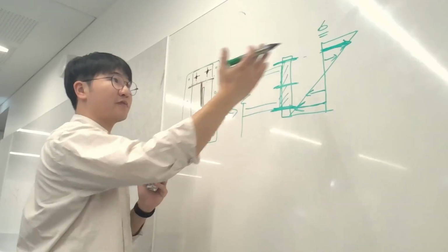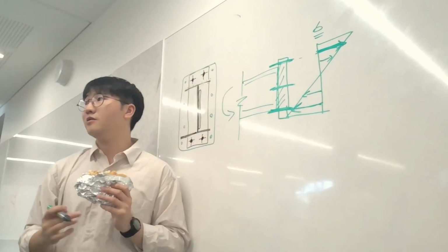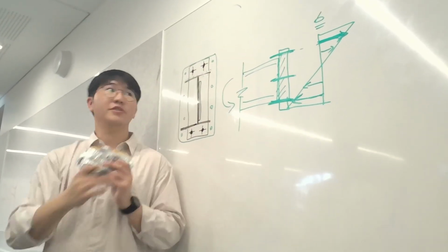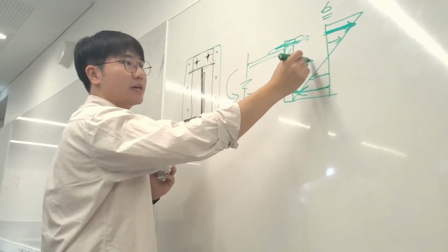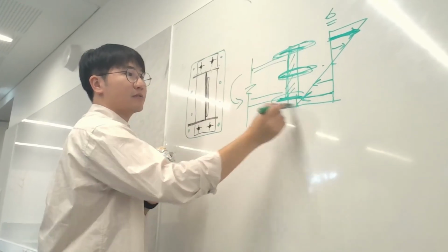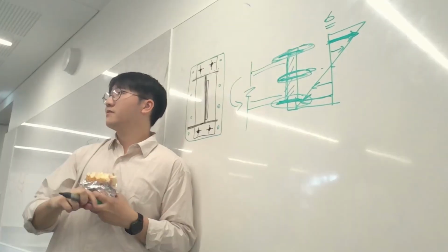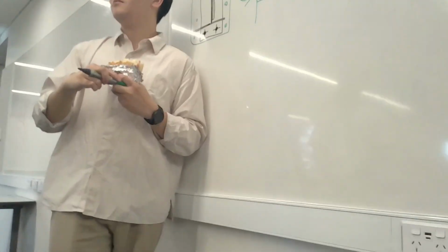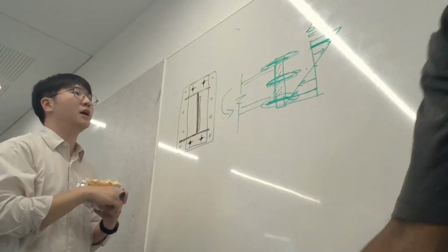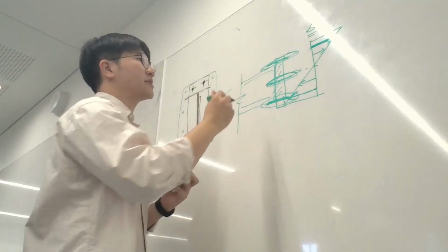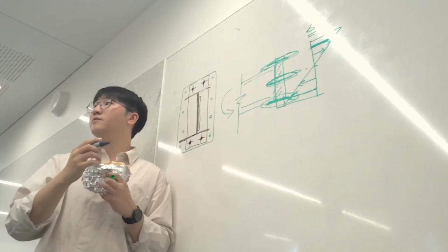So this is called out of plane bending of your bolts, which induces axial forces in these bolts. So that one's not really experiencing any. That one's in tension, that one's in compression. So it extends further than the I-beam itself goes to the end of the plates. It's just straight, yeah. Yes, because the plate itself is bending.